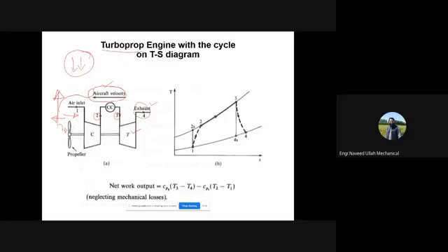And if you remember these two are not mounted on the same shaft, right? If you remember, we discussed this thing in the gear train, that the RPM, the speed of this turbine and compressor, they are in thousands, okay, in 3,000, 4,000, 5,000, but you cannot rotate this propeller with the same speed. And the reason I told you, okay, it can even break the blades of this propeller if you rotate this with very high RPM, right? So for that reason, there is a reduction gearbox installed over here that reduces the speed of the shaft, okay, and rotates this propeller at a reduced speed.